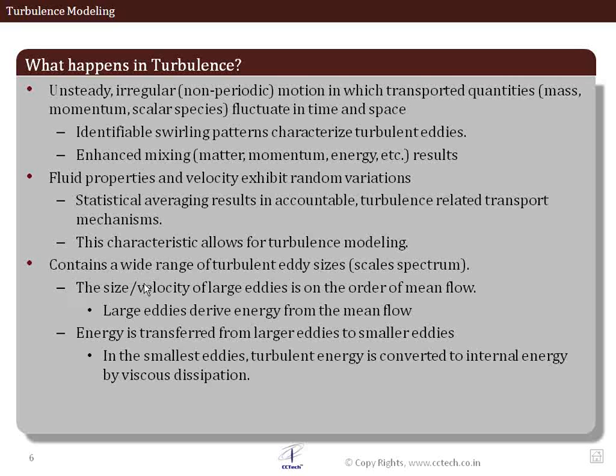And we are going to speak about the concept of energy cascading in this regard. But basically, turbulence results in a loss of pressure energy. It results in a loss of the flow energy which is driving the flow. It is lost, and therefore the question comes that there are situations when we would like turbulence because it would enhance our heat transfer coefficient, it would enhance the mixing of the different species, but it comes at a cost of the loss of pressure.